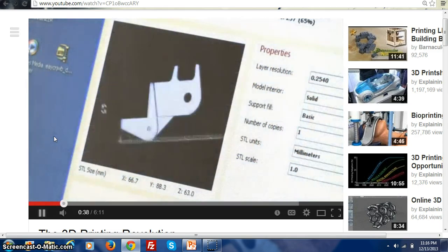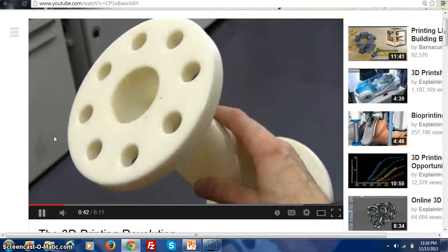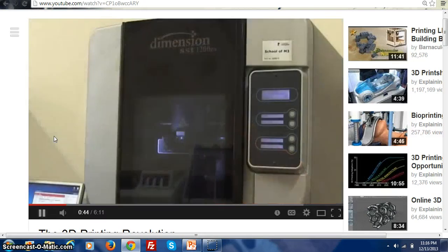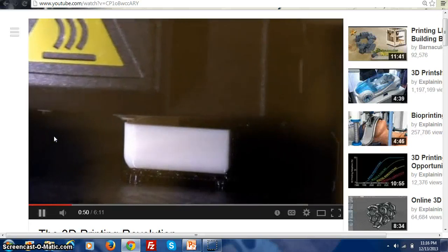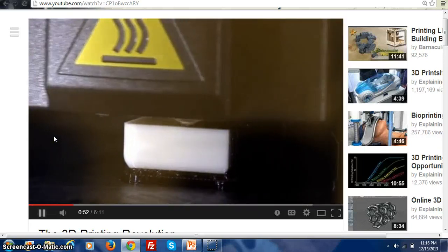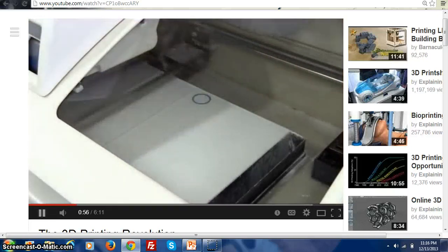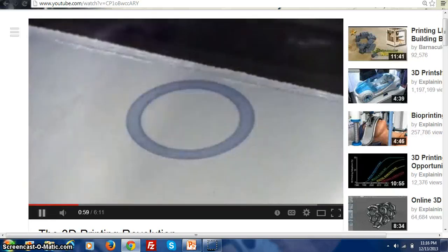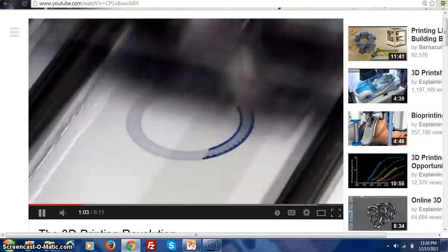3D printers turn computer models into real physical things. They do this by building up an object in a great many very thin layers. Some technologies achieve this by extruding a molten material, such as a standard thermoplastic, from a print head nozzle. Other technologies lay down successive layers of powder that are selectively fused solid with a laser beam or other heat source, or else bonded with a spray-on adhesive.